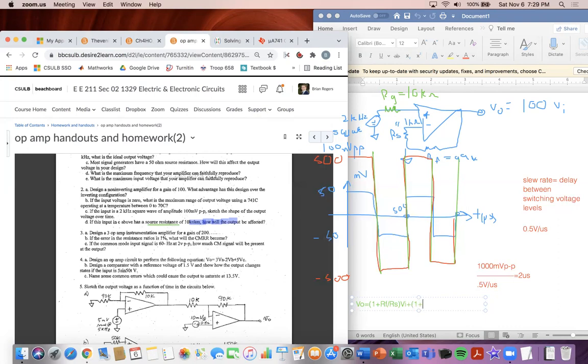So it's exactly the same, RF divided by RS, times the V offset, plus, and then the third one is the input bias currents, which I just remember as VP minus VN times the gain. So IP RG minus IN, and then if it's 0 volts the output, which it should be when you're determining input bias currents, RS is going to be in parallel with RF.